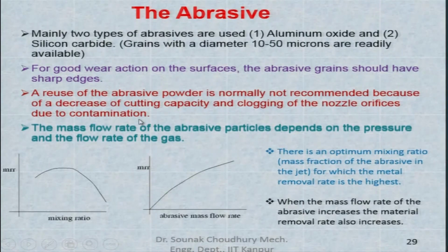So, normally the abrasive powder which has already been used once is thrown out, because each of the grains will be worn out. Their cutting ability will be less, and they will consume more power with rubbing, without giving the proper accuracy and quality of the workpiece.